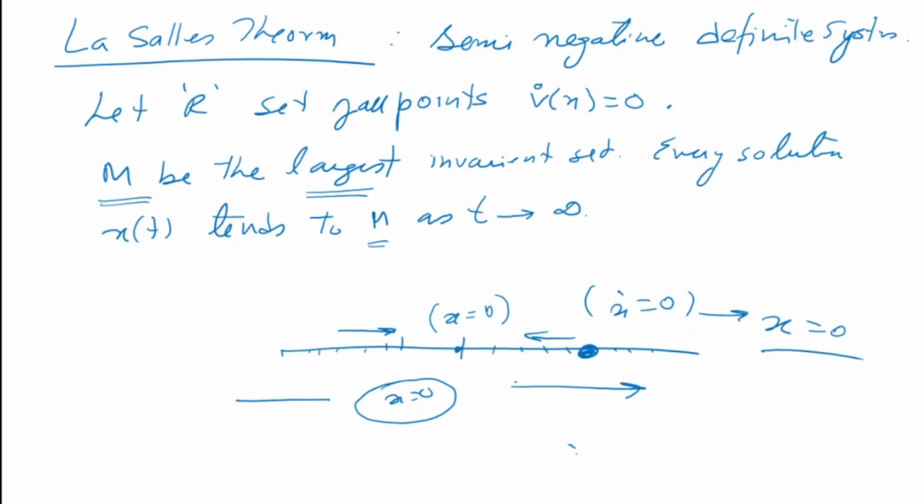So Lyapunov's theorem says that as a sufficient condition, if it is negative definite, then there is no question that it is stable. But if we end up with a semi-negative definite system like a spring mass damper system, then it is also stable using the corollary, LaSalle's theorem, which says that if all the points at which x dot is equal to 0 tend towards x equal to 0, the equilibrium point, then the system is stable. So LaSalle's theorem along with Lyapunov's second method can prove the stability of a spring mass damper system. Now, can this be applied to other systems?